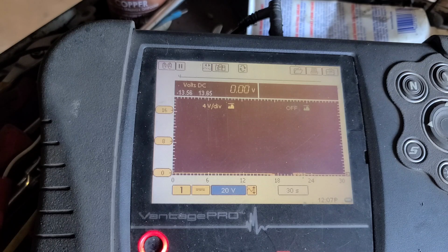Now the circuit in question is pin D. That's setting the fault code. I wish GM would tell us how it tests the circuit. I've got the trailer 7-pole plug connector disconnected, and the fifth wheel trailer harness isolated.